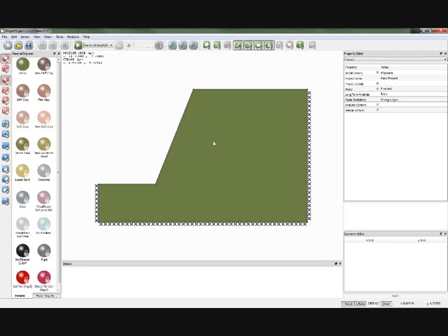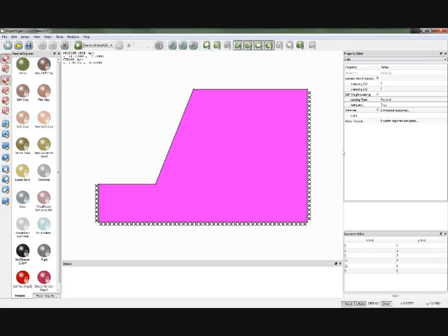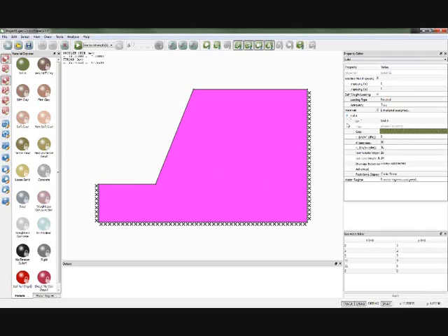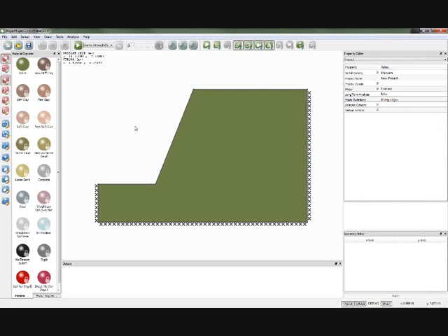Anything I click on in the software, its properties will appear in the property editor on the right. So if I click on this block here, the properties of this solid appear on the right, and it tells me what soil I've got in there. And I've got a soil which is an always undrained soil there and has an undrained shear strength of 50 kPa in this case. If I want to solve the problem, I've got a choice of solving it using what we call factor load or factor strength modes. Factor load is a mode where we have to specify a particular load in the system, and the software will tell us how much bigger that load has to be to cause collapse.